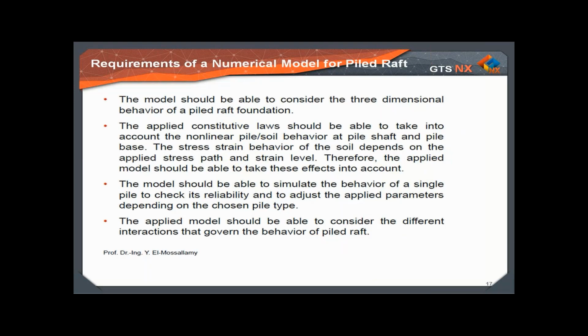What will be the requirements of a realistic numerical model for a pile raft? The model should be able to consider the three-dimensional behavior of a pile raft foundation, so we need to think in 3D for that. The applied constitutive laws should be able to take into account the nonlinear pile-soil behavior at the pile shaft and pile base, and the stress-strain behavior of the soil depends on the applied stress path and strain level. Therefore, the applied model should be able to take these effects into account as well.